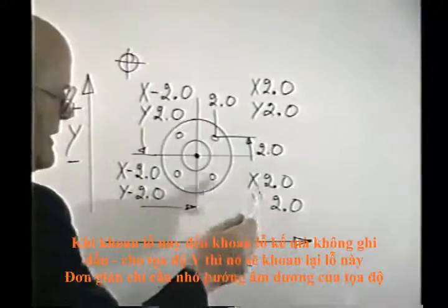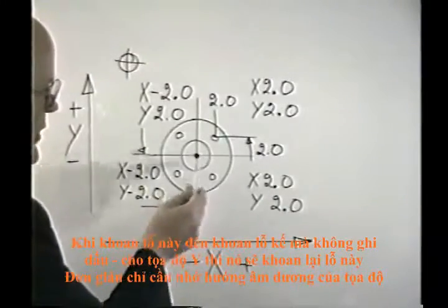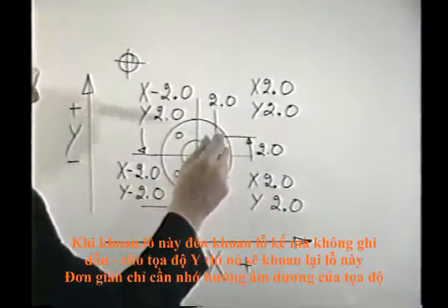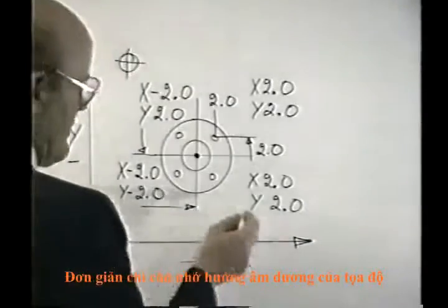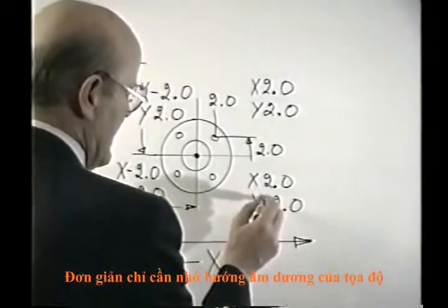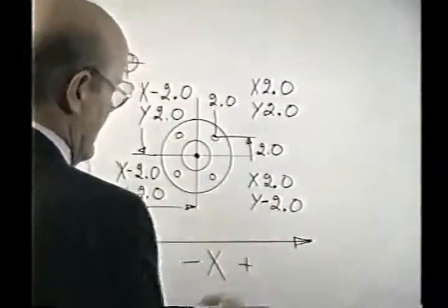The control would think that we're asking it to drill another hole at the same location, and it would just drill this hole twice. So once you see this happen, where you forget a minus sign, it's very easy to remember where these signs are actually supposed to be.